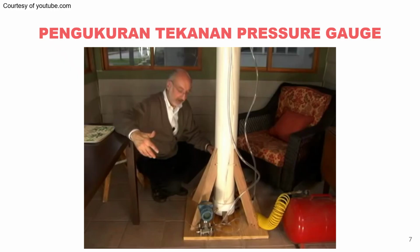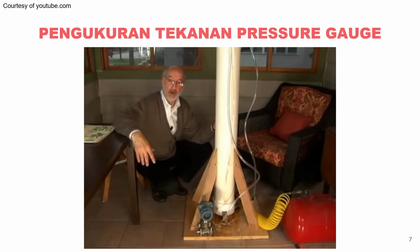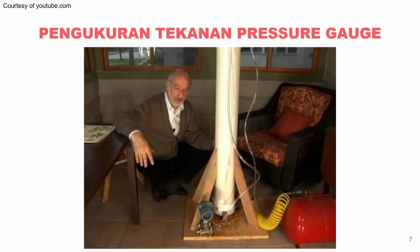You probably want to stay away from things where there's going to be sediment, because the sediment might have a tendency to clog the impulse line, or you just have to put the impulse line somewhere above the sediment level and compensate for it. If you're measuring something other than water, if you're measuring something heavier or lighter in density, you can compensate for that as well. You could do it using a mechanical gauge if you wanted, even a mechanical differential pressure gauge if necessary.